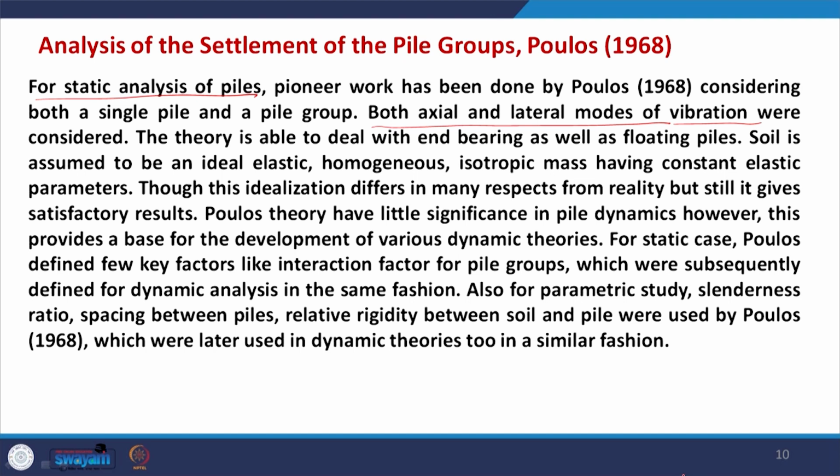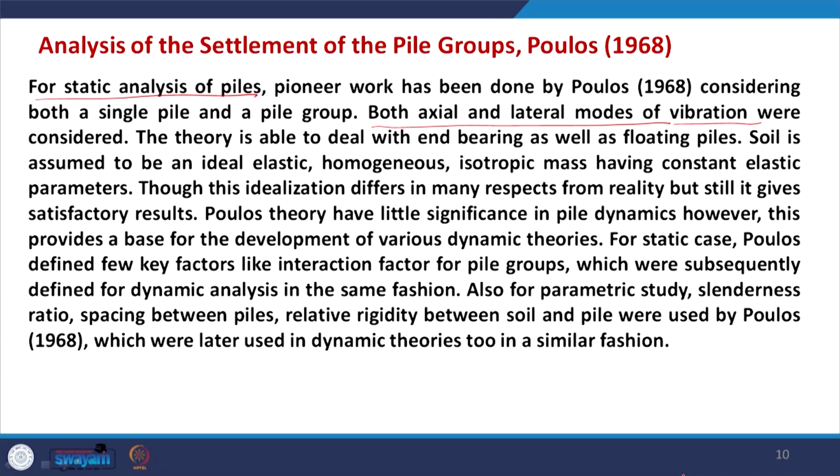However, the soil is assumed to be an ideal elastic homogeneous isotropic mass having constant elastic parameters. That means nonlinearity of the soil is not considered, inhomogeneity is not considered, and anisotropy is not considered. Though this idealization differs in many respects from reality, it still gives satisfactory results. And when we talk about pile dynamics, the Poulos theory may have little significance because they have considered static load, not dynamic loads. As a result, the frequency of loading or natural frequency or the dynamic response does not come in the picture. However, this theory provides a base for the development of various dynamic theories. For the static case, Poulos defined a few key factors like the interaction factor for pile groups.